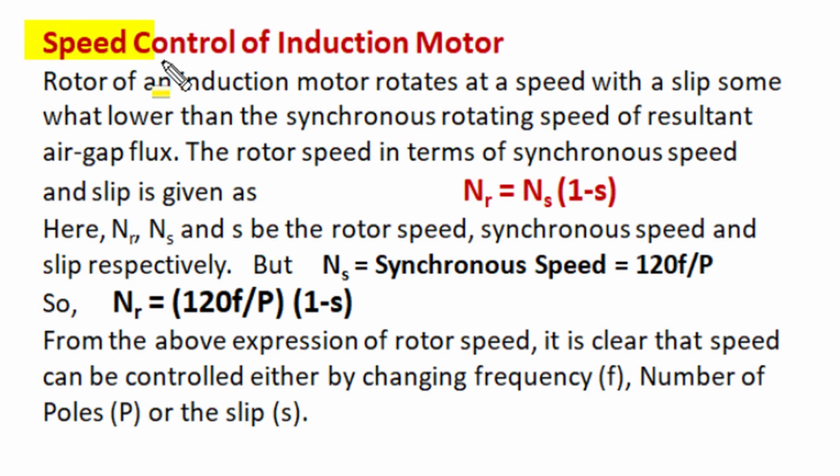Let's understand the theory of speed control in an induction motor. In an induction motor, when a three-phase space displaced winding is excited by three-phase time displaced excitation, then between stator and rotor in the air gap, a rotating magnetic field of constant magnitude and constant rotating speed gets produced. The speed of rotation of that rotating magnetic field is called synchronous speed, Ns in RPM, and that speed depends upon the frequency of the three-phase supply given to the stator, F, and the number of poles for which stator and rotor are designed, that is P. So for F frequency and P number of poles, the rotating magnetic field speed called synchronous speed in RPM is given by 120 F over P.